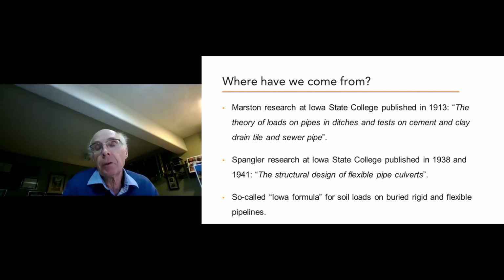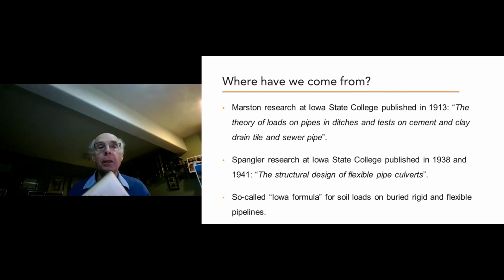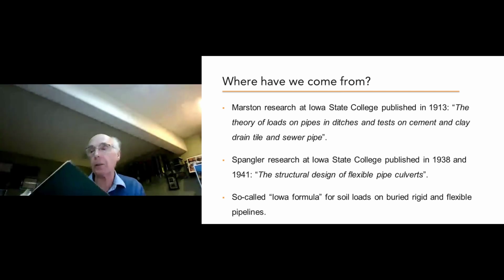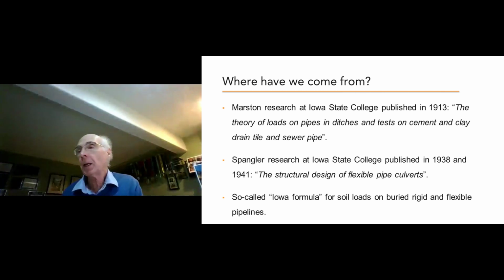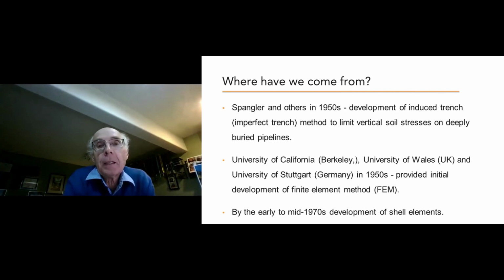And Spangler and Marston were not alone in this. Even Terzaghi, in his 1948 publication of Soil Mechanics and Engineering Practice, talks about soil loads and the concept of arching. And the Iowa formula, including things like the induced trench method or the imperfect trench method, was developed at Iowa State. And that has very important implications, for example, for HDD installations.